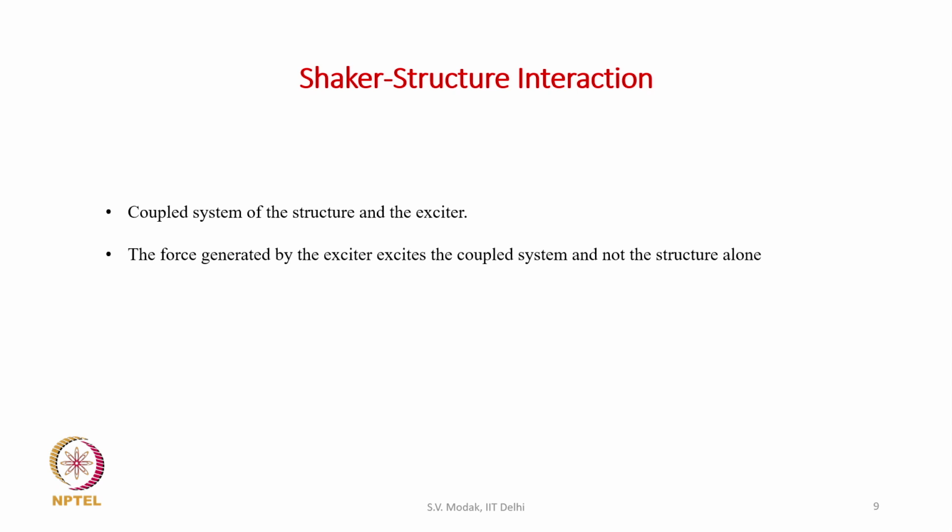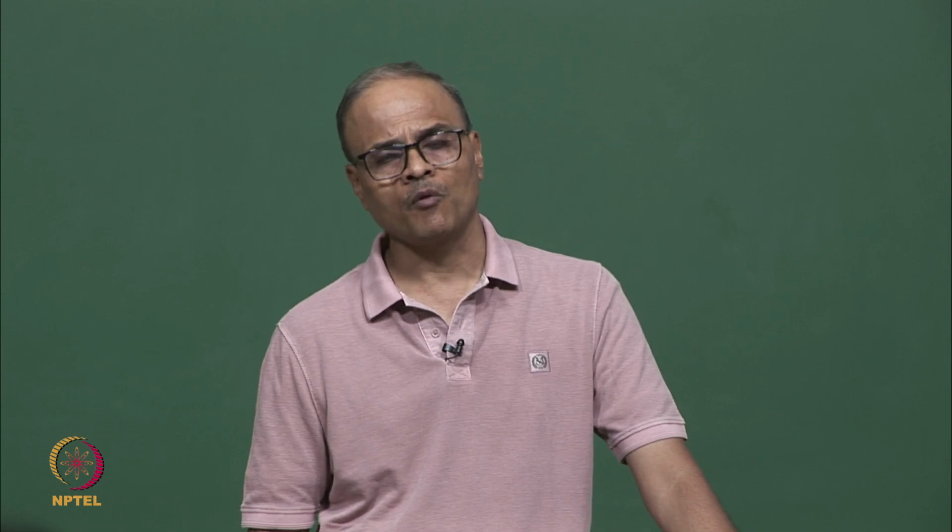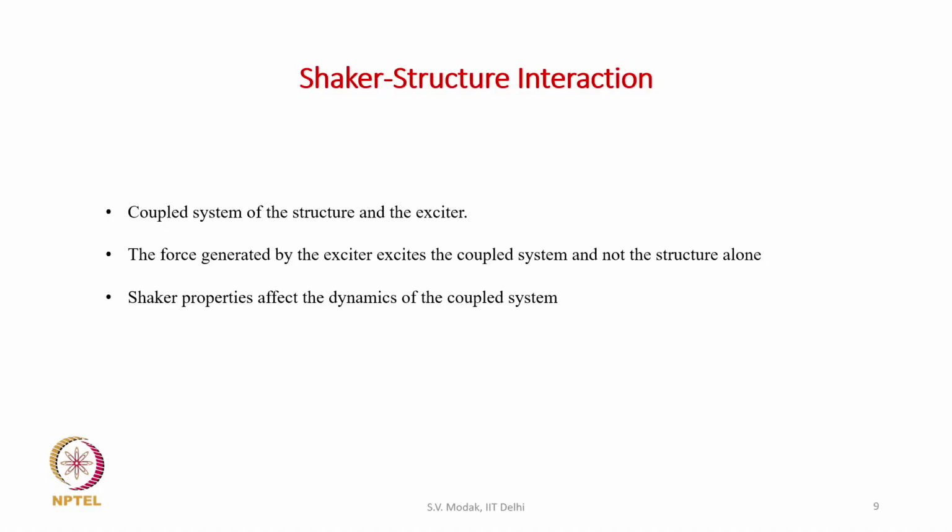Another thing is that the force generated by the shaker vibrates not only the structure, but also the shaker mechanical system. So, the force generated is shared by the structure and the shaker, and therefore the shaker properties also affect the way this force is shared. Therefore, by analysis of the interaction between the shaker and structure, we would like to figure out what measurements we need to take in order to identify the dynamic characteristics of the structure.